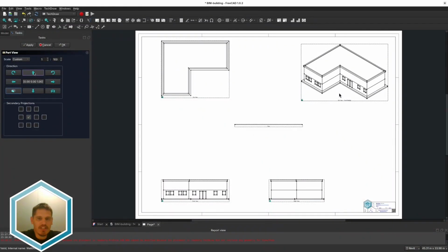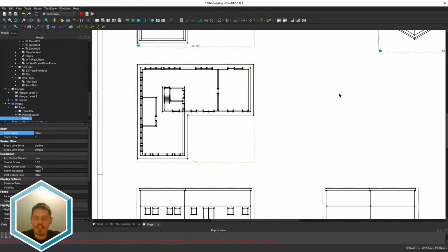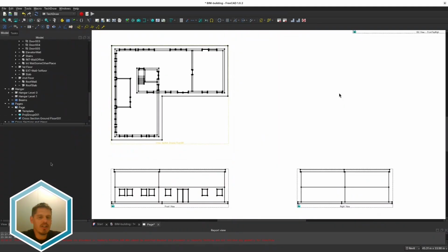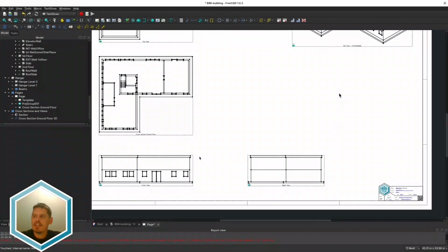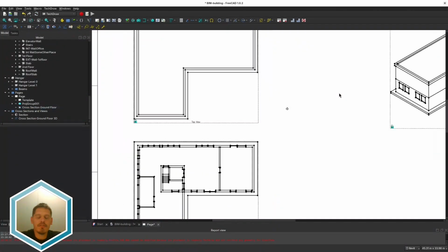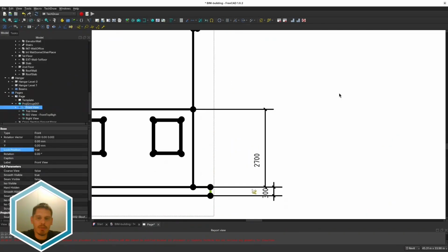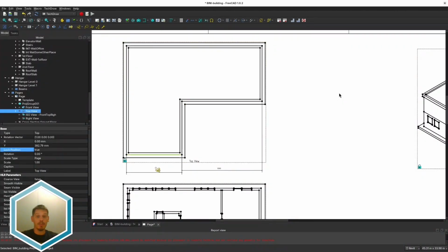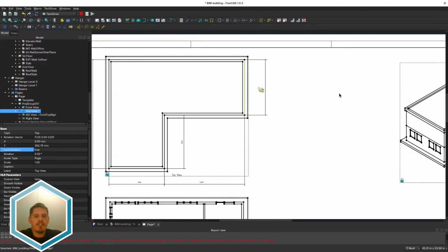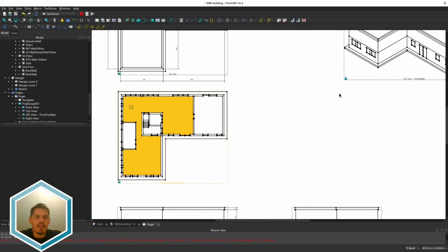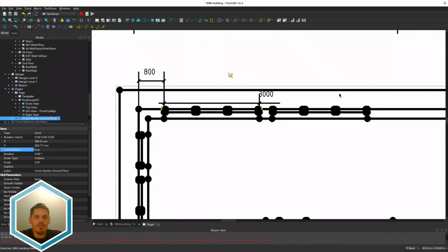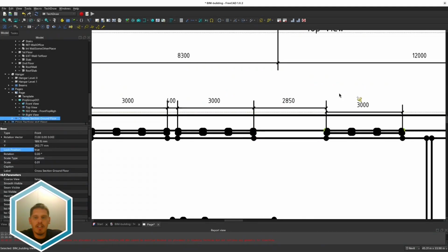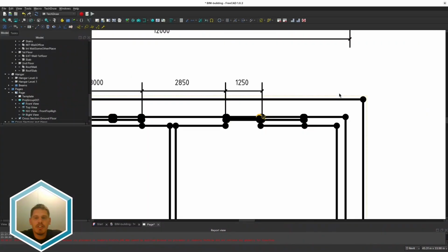But then they completely select the wrong size of the page frame, and it throws off the scaling of your drawing. It's not wrong to set it up right: just set up your frame around the page with the correct margins in either model space or paper space, whichever is your own preference or your company's preference. And then just set it to layout, and you don't ever have to bother with that again. You just make the page, make sure it has the right template of the right size, and use layout. You never have to worry about the scaling being off.